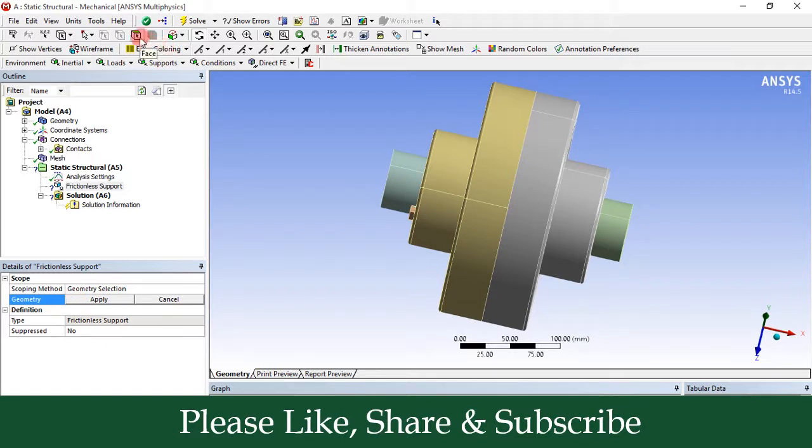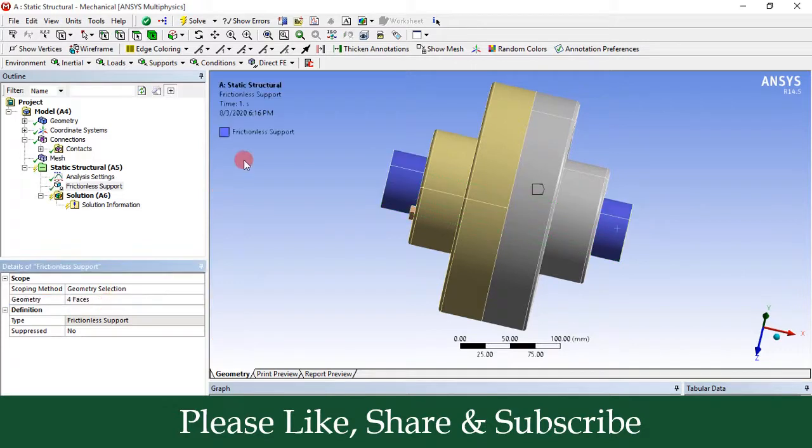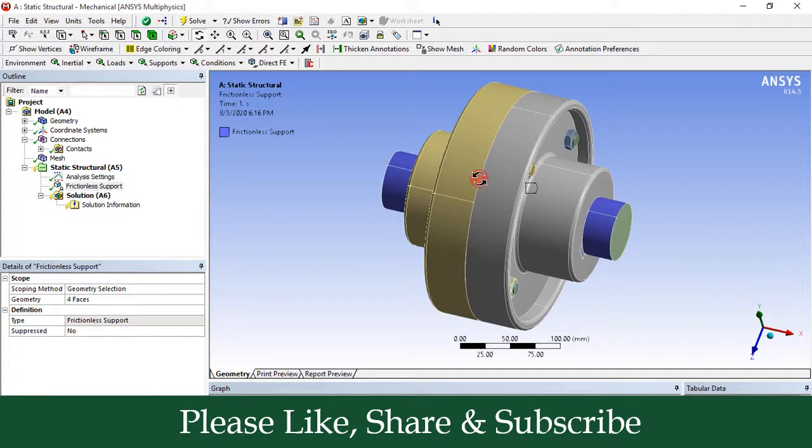So go to the face selection button, select this cylindrical face of input shaft, similarly cylindrical face of output shaft. So I have selected two faces of input shaft and two faces of output shaft. Now click on apply button. Now in this way I have applied the frictionless support on input and output shaft.